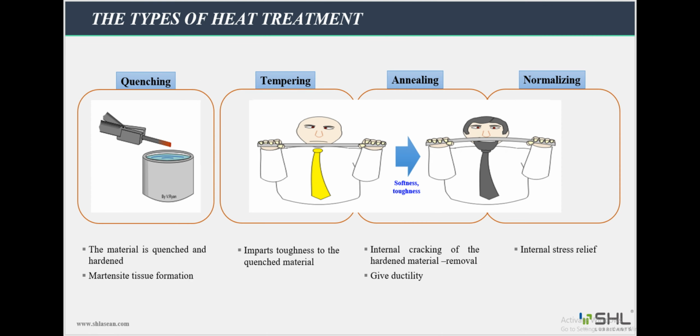Regarding heat treatment methods, there are 4 main methods: quenching, tempering, annealing and normalizing. The quenching method is a method of heating the metal above the upper critical temperature, then keeping the heat to stabilize the martensite structure and then quickly cooling. This method increases the material hardness but with low ductility. The second method is tempering, which is similar to quenching but is heated to below the lower critical temperature, keeping the heat for a while so that the metal structure is evenly distributed and then cooled to room temperature, to increase the ductility of the material.